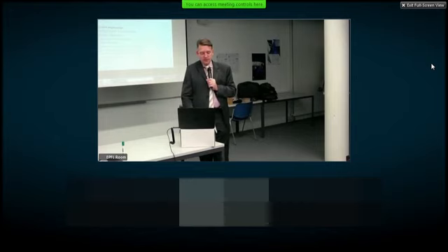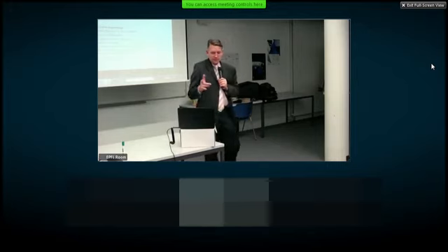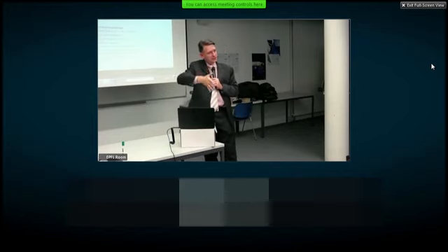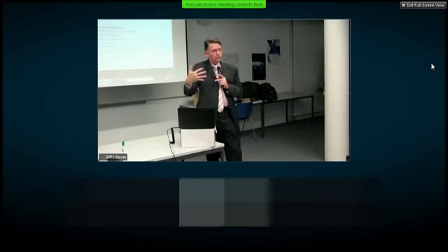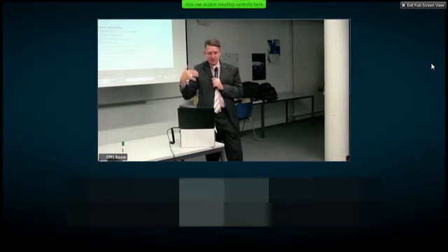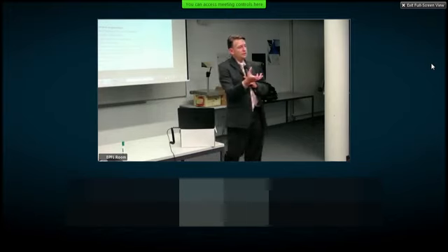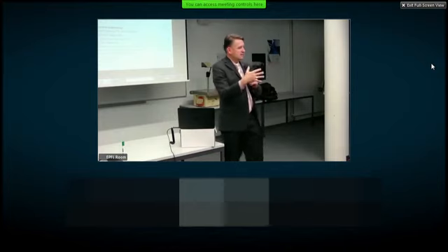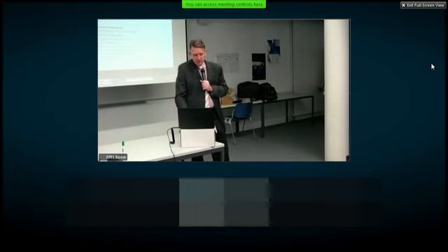And then the other way to do it is bottom-up, where you already have a design or a system. You decompose it. For example, you do product dissection. You do your bill of materials or your parts list. Then you do your liaison diagram, right? You show the physical connections. And then on top of those physical connections, you map your mass, energy, and information flows. And once you have that, then you can start manipulating the DSM. You can group components differently. You can show modules and so forth.